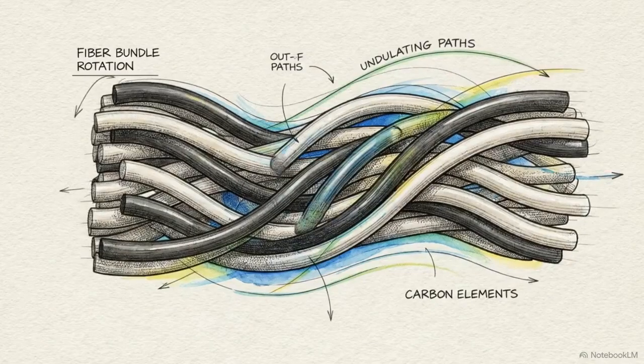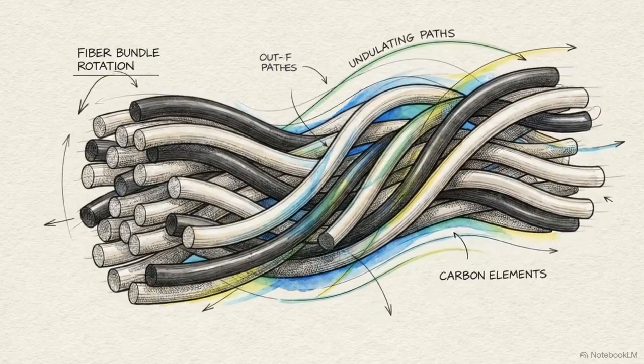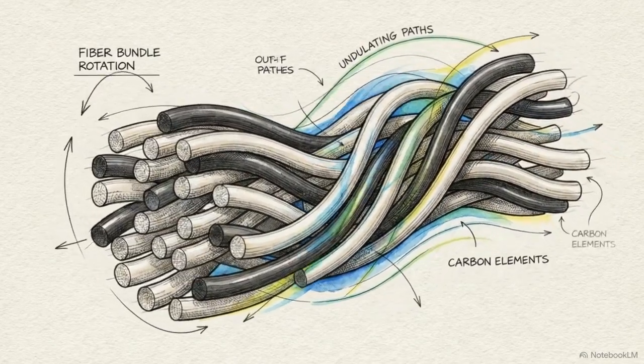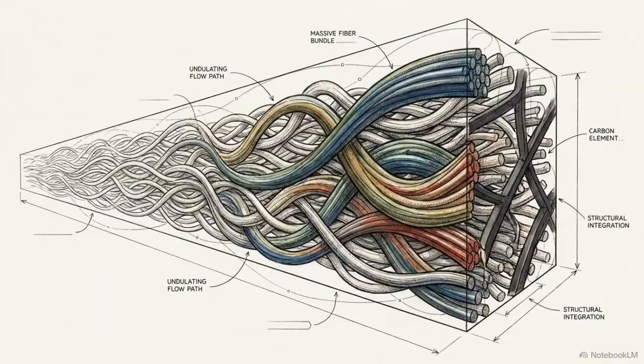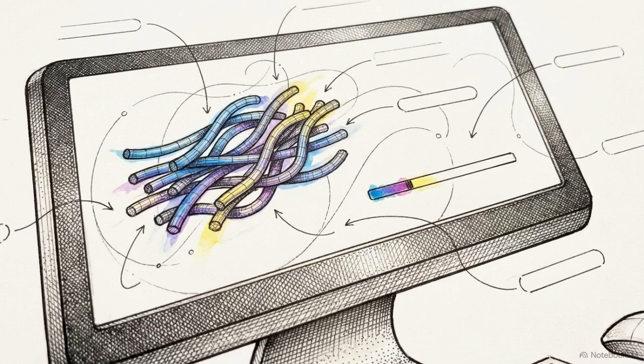In 3 dimensions, fibers do not run in perfectly straight lines. They exhibit continuous, wavy paths and out-of-plane misalignments along their longitudinal axis. Capturing complex 3-dimensional waviness requires massively scaled representative volume elements, containing thousands of individual undulating fibers. This introduces a severe computational bottleneck. Simulating thousands of wavy fibers using traditional 3-dimensional continuum finite elements takes days or even weeks of continuous processing time.